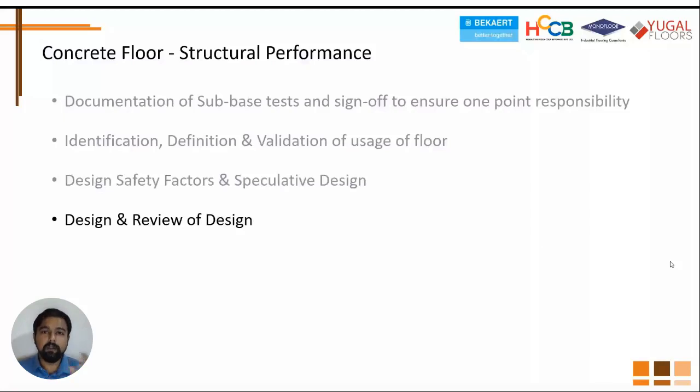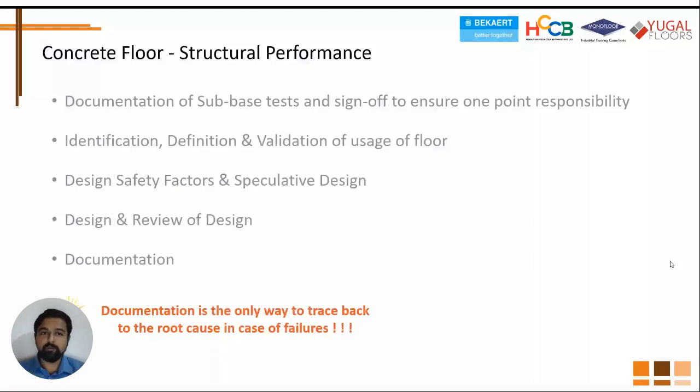So it is important to design. It is important to review the design. Even if the flooring contractor is given a design and build form of a construction contract, it needs to be established whether the design is sufficient. So a design review is also very important, and so is documentation for all these parameters that we've been talking about, so that if we have a problem, we can go back and trace. Documentation is the only way to trace back to the root cause. Touch wood, if you have a failure, documentation is the only way to check what you designed for, what loads you expected when designing the floor, what the subbase was before construction of the floor started, and all of this.